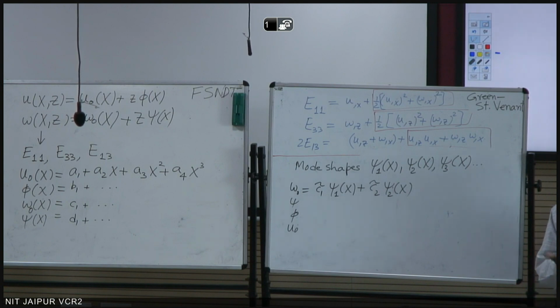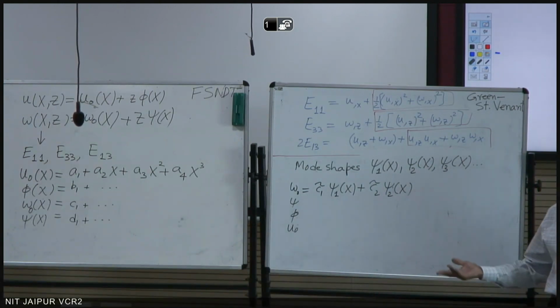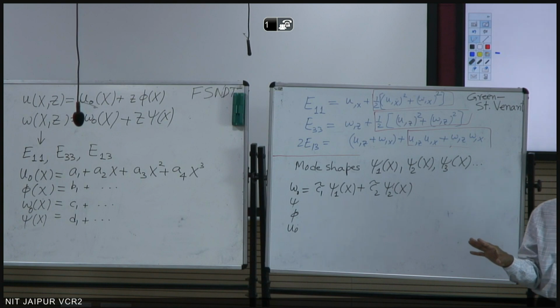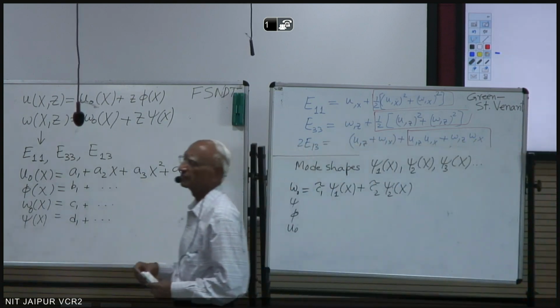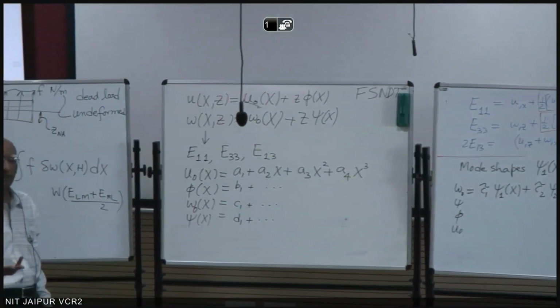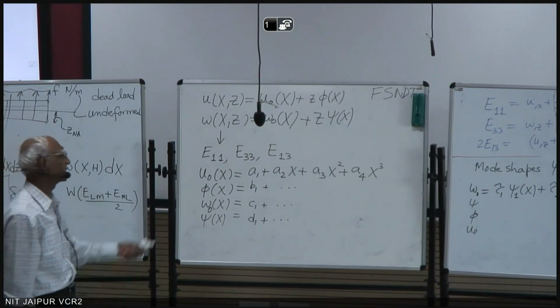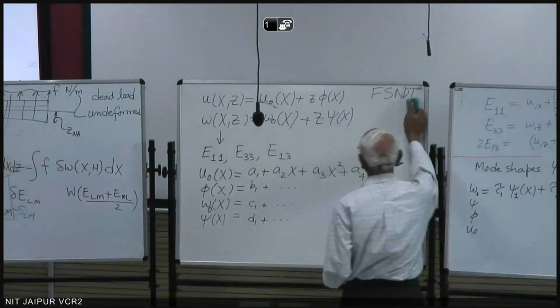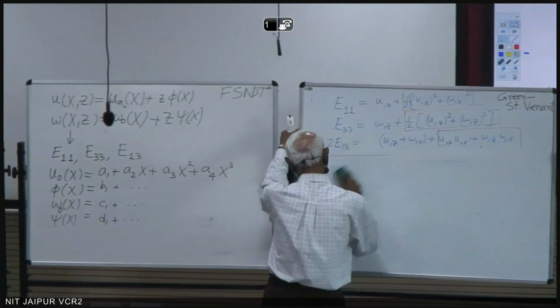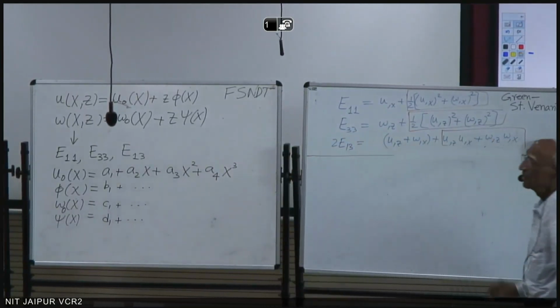And yeah. So if you go back to the same thing, it's your choice. Remember, the choice of the basis functions will determine the quality of your approximate solution. If your choice of basis function is very good, you can survive with one or two unknowns. But if it is poor, then you have to take more. So let's stick with this because I don't need to find the mode shapes and I don't need to find the frequencies.